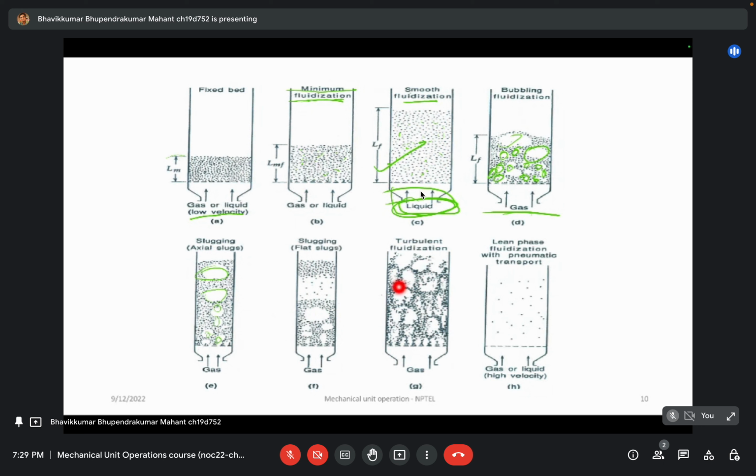You can't predict any particular shape or size, and the pressure drop at each and every space is not the same. They are all different, and you can see a different pattern, like a turbulent flow, and it's known as turbulent fluidization.